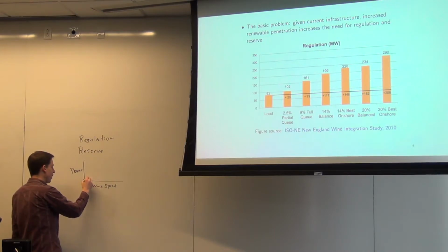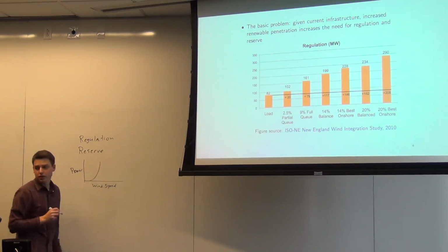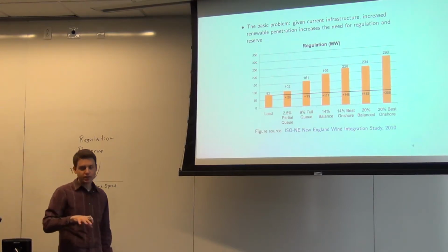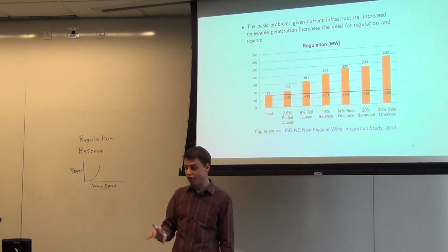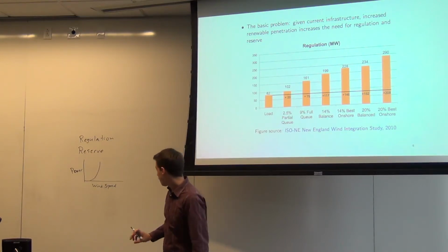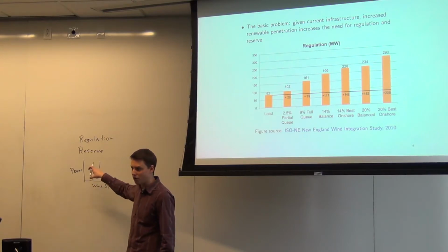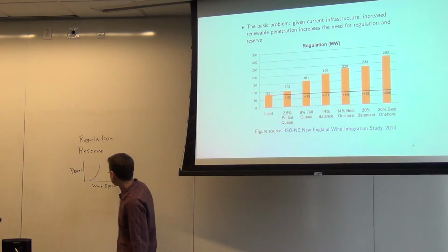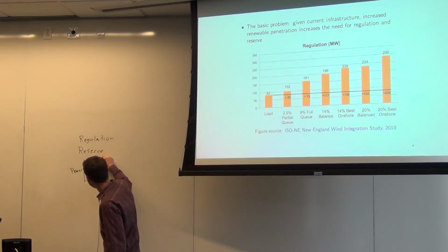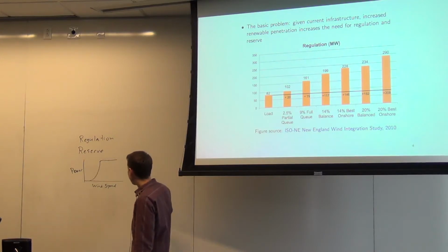Then once you start generating power, you actually start increasing with the cube of the wind speed. So power in wind, if you just look at the physical equations, is actually proportional to the cube of the speed of the wind. So there's some range here where a 1 mile per hour increase in wind speed gives you a whole lot more power. And then what happens is that you tail off. You can't keep this going on forever because the turbines reach their capacity, and so you tail off here. And then eventually, they even shut down.